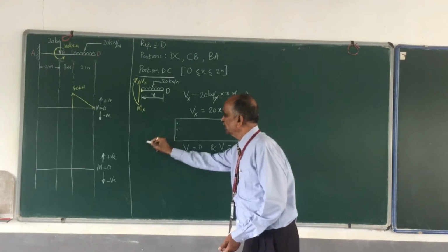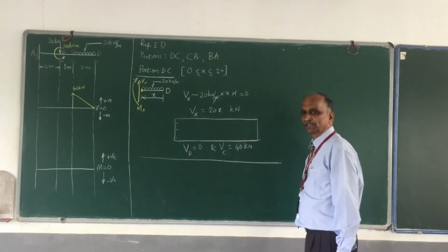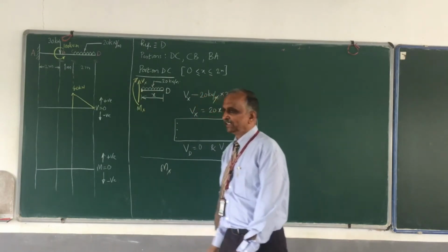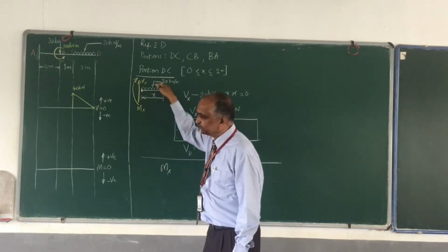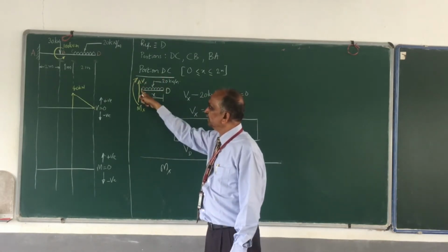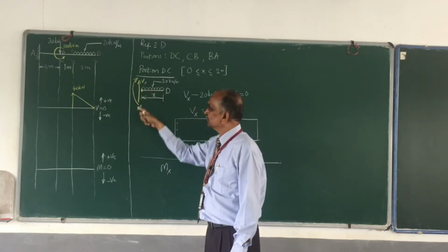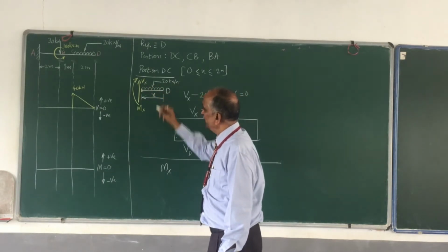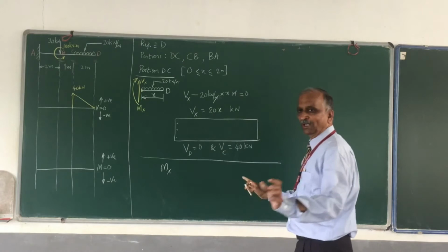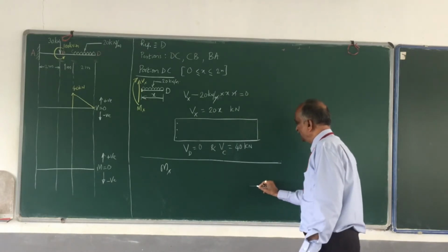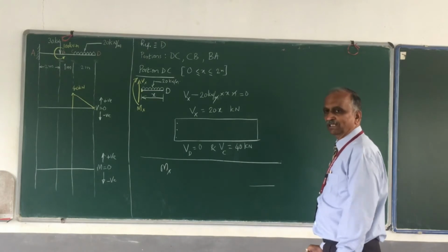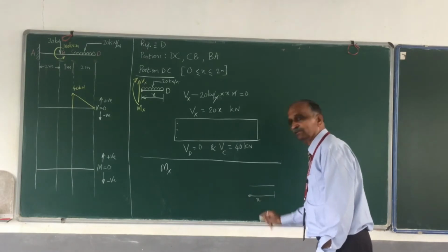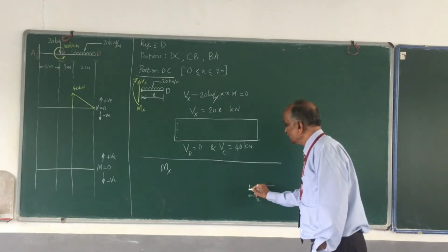Okay, let me complete now. Go for the bending moment. Start with Mx. Unknowingly I have made a sign convention. What is that? The clockwise moment is positive. I am taking moment about this section due to all the forces. Vx is there only, therefore it will not have any moment. Now I have a moment. For bending moment, whenever you have UDL, please draw one more diagram here. No problem. You can spend a little more time, and you can't afford to make very silly mistakes.